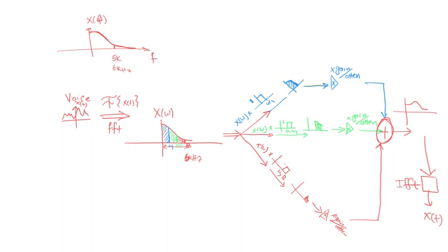without really converting the signal from one thing to the other. It's just the audio comes from the microphone, it goes into the RC circuits, which are designed so that one is the lower band one, and then another one designed to approximate the band pass, and then another one designed to approximate the high pass, okay?